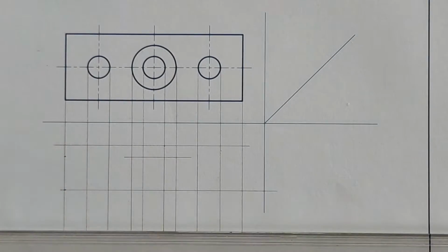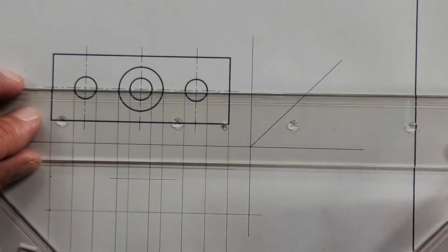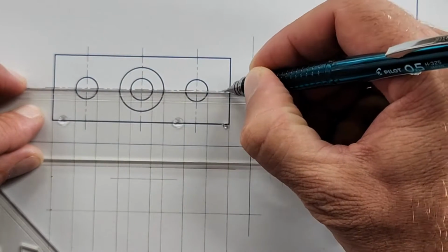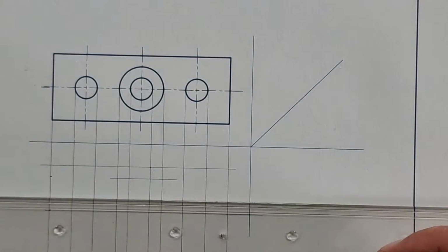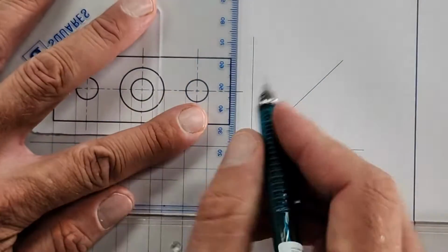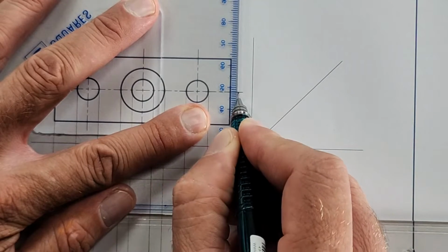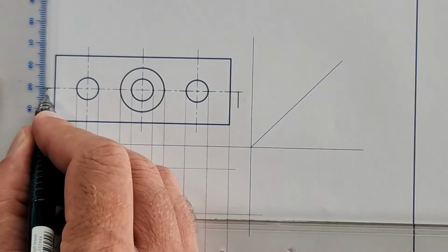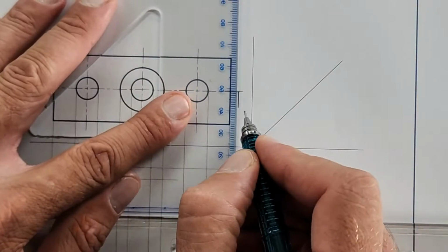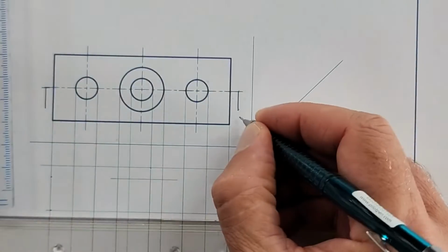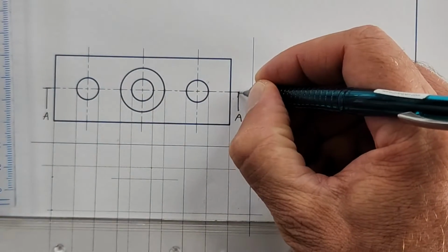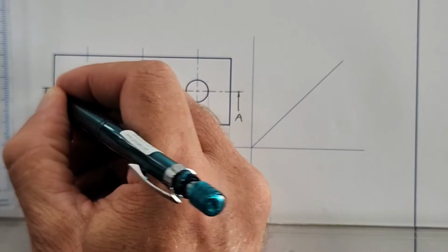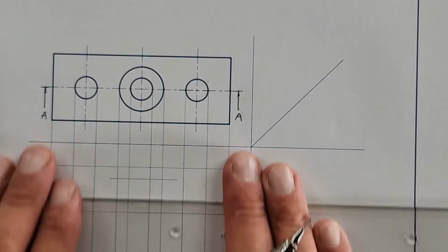Okay. Now if I would put the cutting plane, you're going to put in the cutting plane first. The cutting plane runs through the center. So here it is. I can redraw all of this, just don't want to waste time. But on this end here, alright, we're going to do the cutting plane indication. It's an arrow like this. Same arrow on this end. Okay, make sure your lengths are the same. We're going to write A, and we're going to put the arrow here. Okay. So we are looking in this direction.